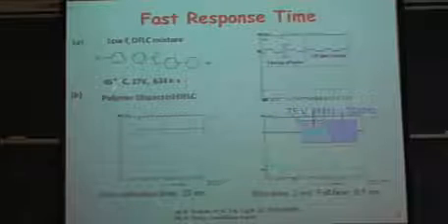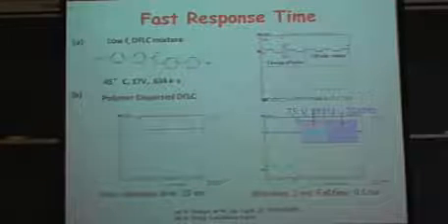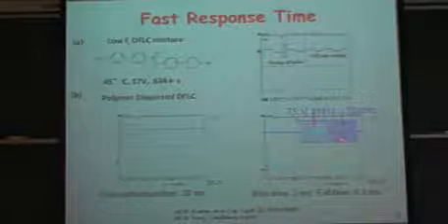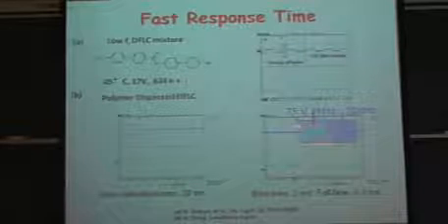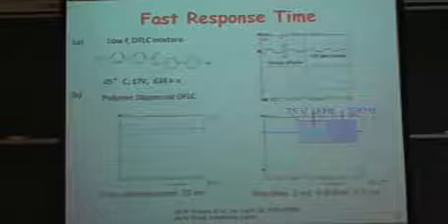When you increase the temperature by 10 degrees, the viscosity drops 2 times. So at high temperature it has low viscosity, and that realizes a 634 microsecond response time. And I use this in the polymer dispersed system, and I fix the voltage at 75 volts and just scan the frequency, 1 kilohertz, 30 kilohertz, and get this 2 milliseconds and 0.5 milliseconds.